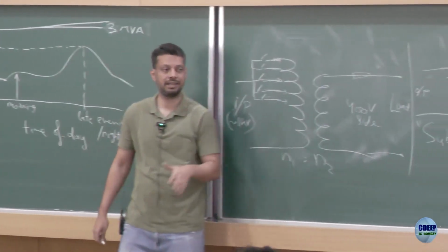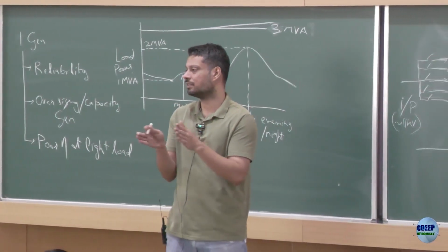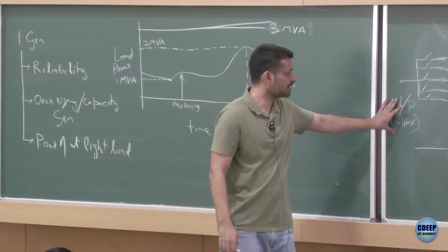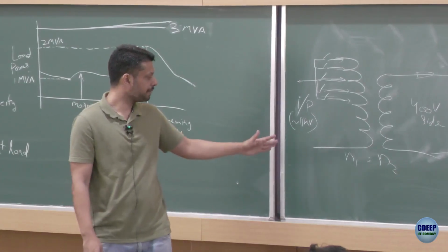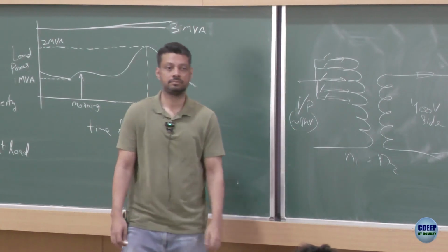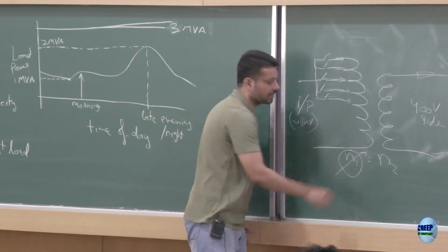So, depending on that, you can write a small logic, and this would make sure that the voltages are fairly well maintained, irrespective of the fluctuations here, irrespective of the load fluctuations. Yeah, and N2 remains the same, we change N1 so that V2 can increase or decrease. So, we change N1, not N2.